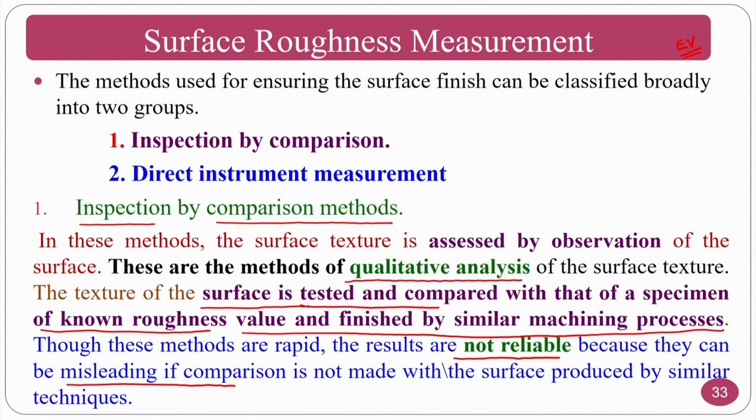Assume that my master sample is procured from some agency, and the sample you have is produced by grinding. If you do not know which process the master sample was prepared from, assume it was prepared from a lapping process, while the lot produced by the company is from a grinding process. If the surface finish is matching, it is okay.